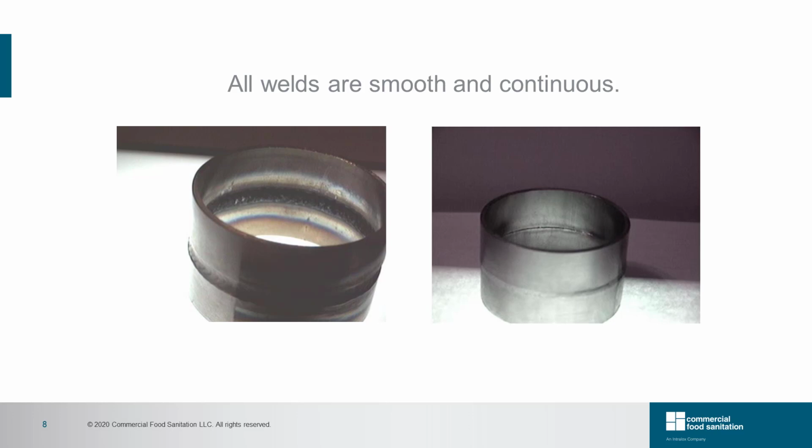In the image on the right, if the weld is not fully filled, microorganisms could become trapped in the unfilled crevice, resulting in a cleaning challenge that will likely promote a product shelf life or spoilage issue. Sanitary welds take craftsmanship and care, which are critical to installation processes.